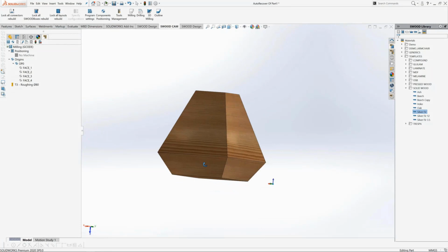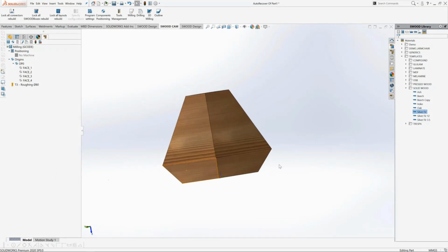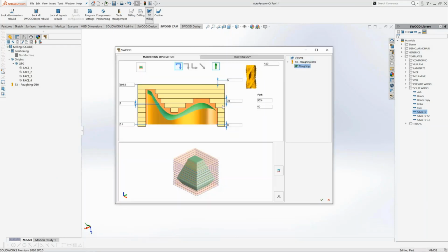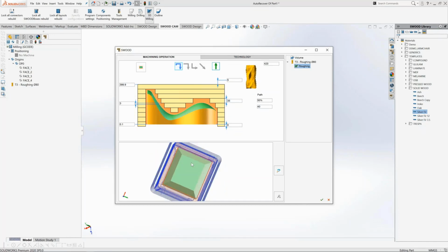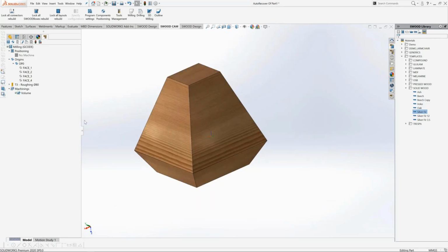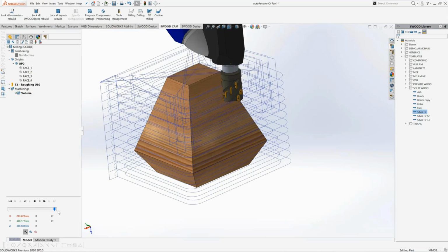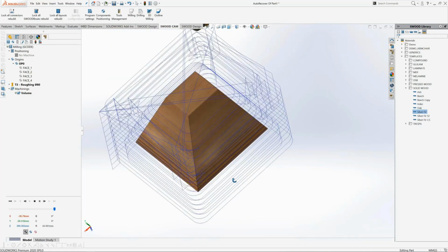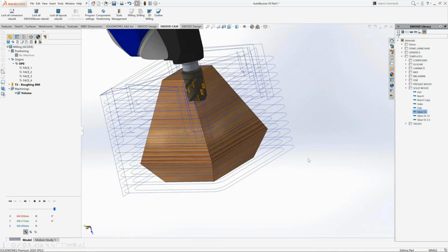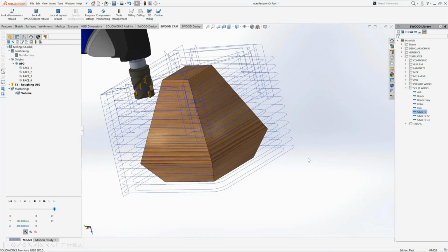So this year in SWOOD 2020, we changed our view regarding the definition of the roughing operation, and we have the option to embed different drafts in the part definition, and we check that in a better way than we used to do in the previous version. For example, here we have a draft on the bottom side, and we'll be able to exclude that directly. We also embed here the stock extension that you are able to define on the panel with SWOOD Design, or the stock extension defined in the CAM program origin. And we can have a better definition of the roughing operation just like that.